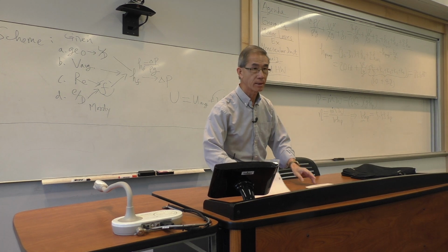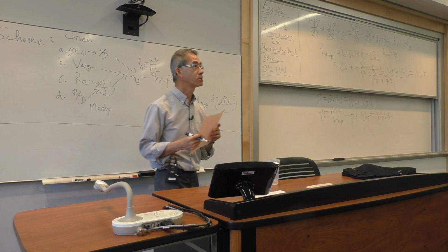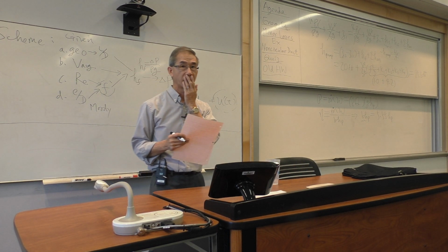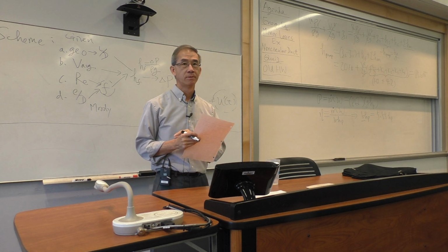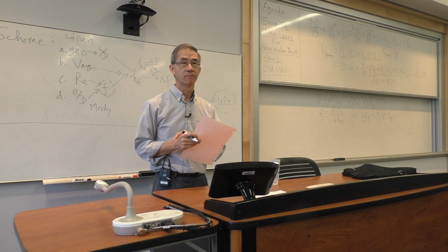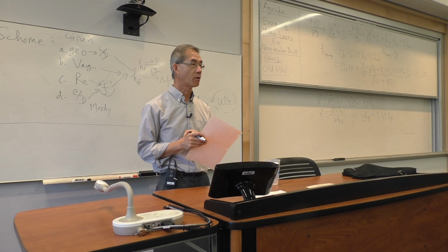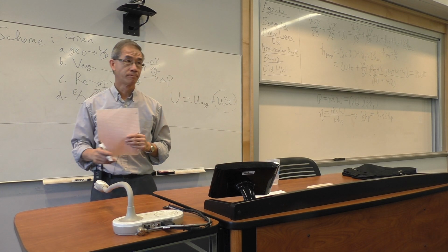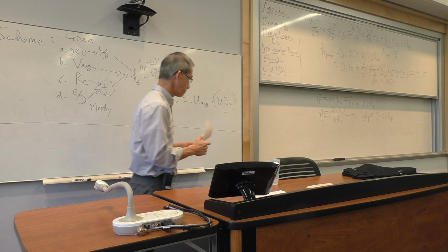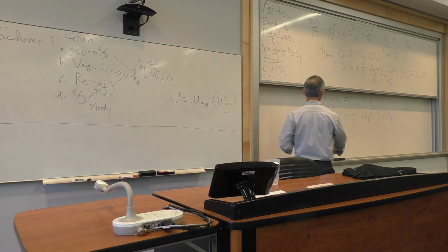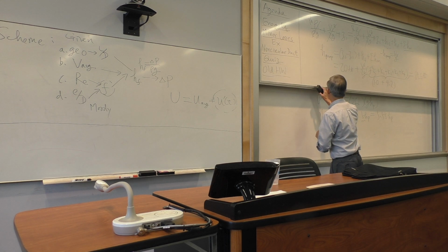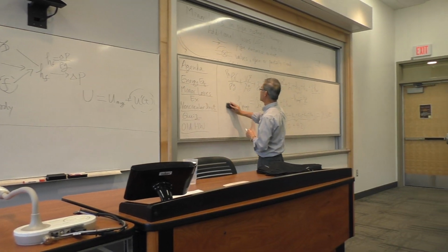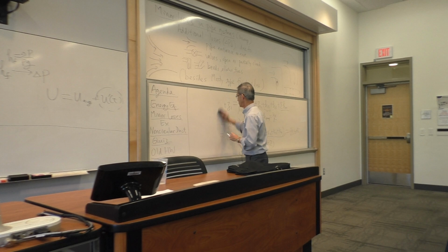So what is the takeaway about the word minor losses? What can you tell me about, is this minor losses really minor? No, by far no, not at all. In most cases, like pumping water or HVAC, there's a significant, big part of the whole power requirement, by far.